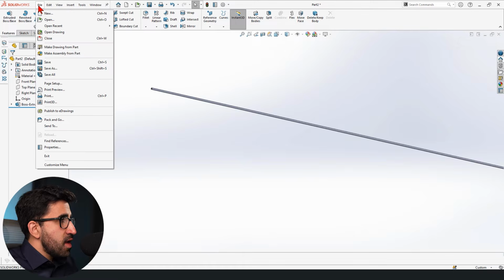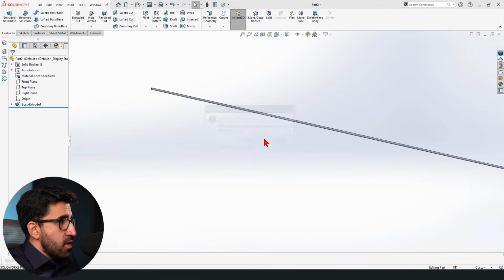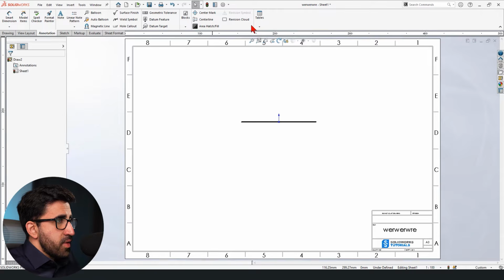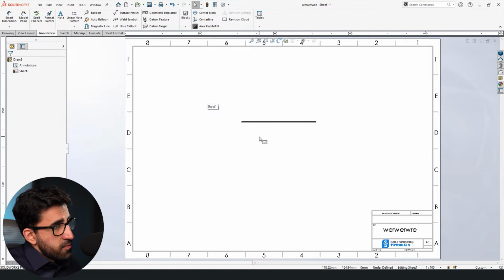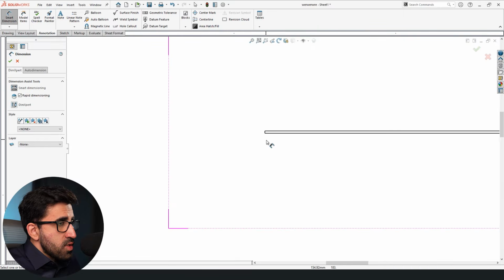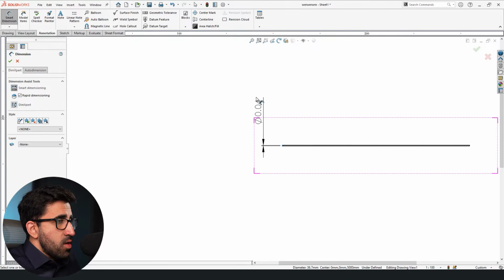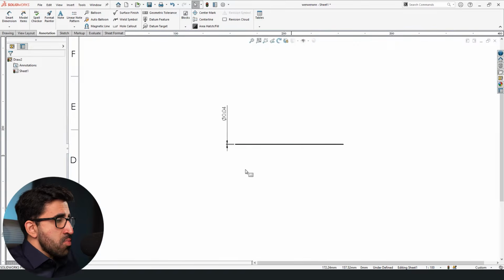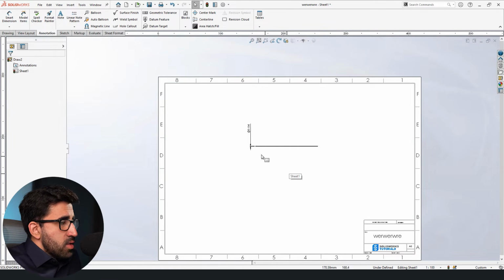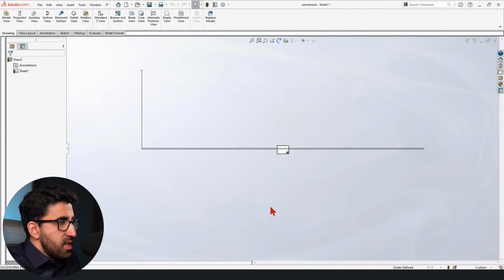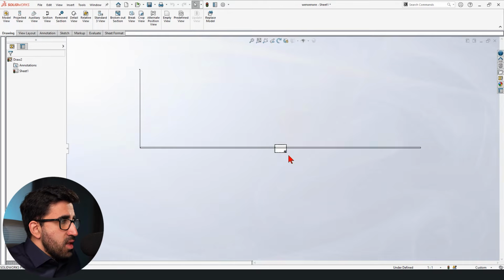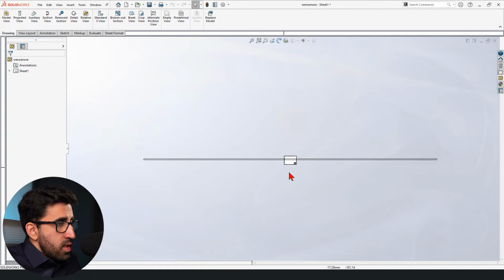And when we want to create a drawing out of this out of proportion component, if I bring that component here, first of all, yes, SolidWorks reduces the scale as much as necessary until it fits onto your drawing. But if I'm going to address its diameter, or even the inner diameter, it's so small that nobody can see anything. So of course, I can scale up my sheet just like I showed you. It's 1:100. Let's just say I want to bring it to 1:1. Then the length of my component exceeds the length of my sheet. So what do I do in this case?